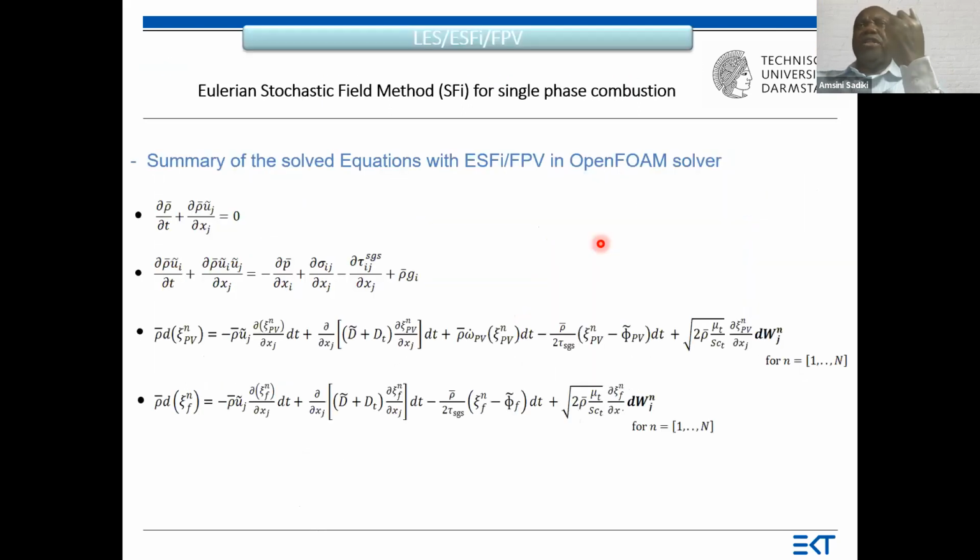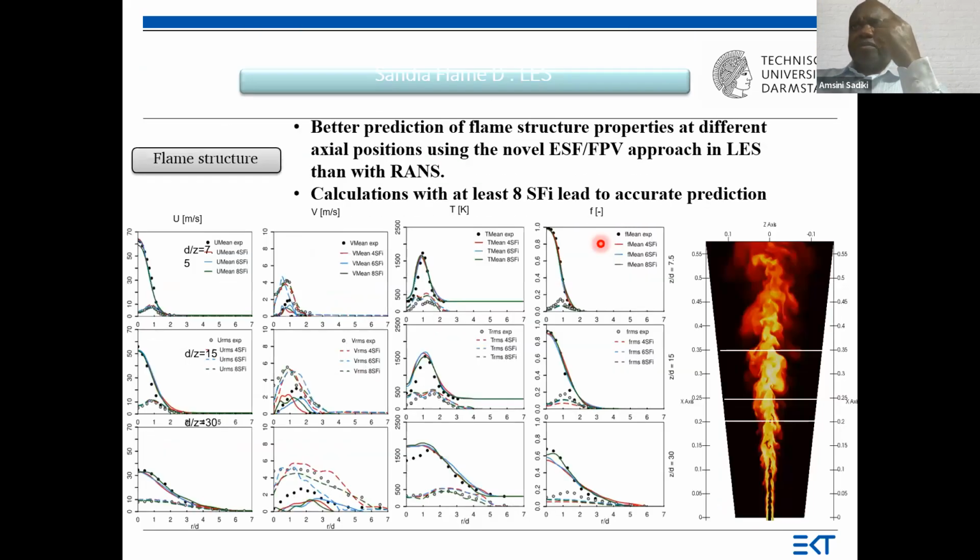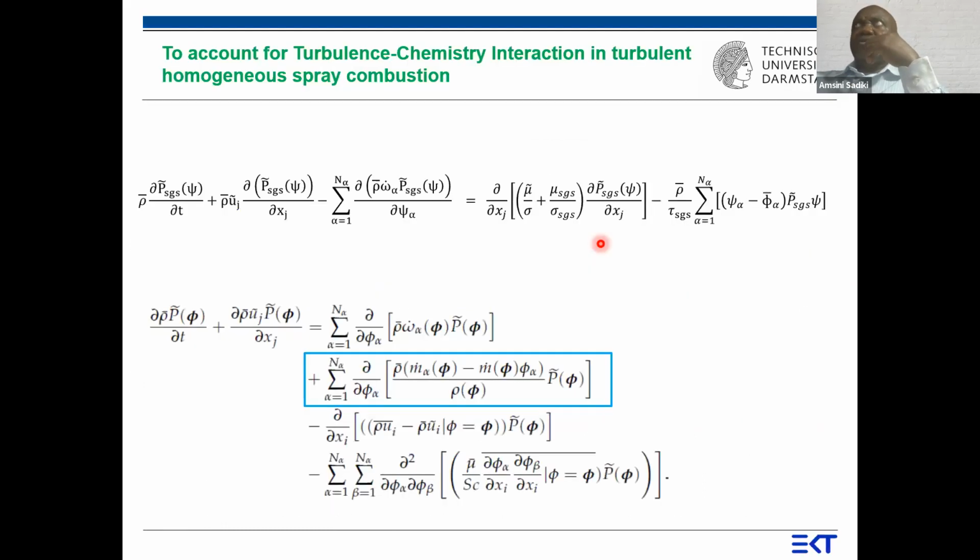So the other point was to show how we can now include not only the effect of flame on the particles or of the particle on the flame this way, but how we can remove all these assumptions. The assumption of ATF, this means that we thicken the flame, and the assumption on the presumed PDF, where we have this restriction on the physics which take place within the flame.